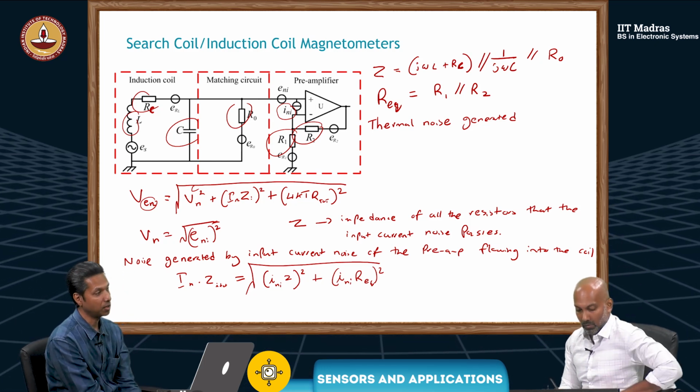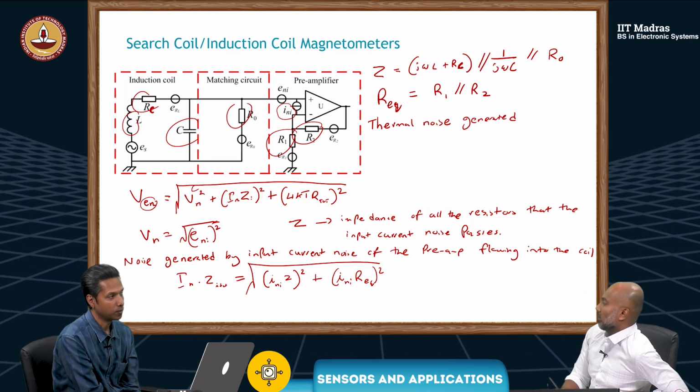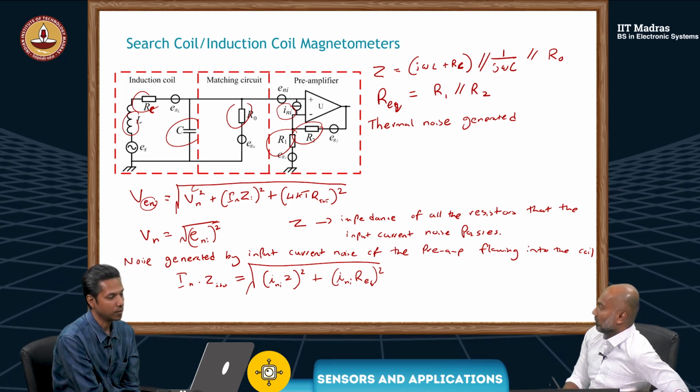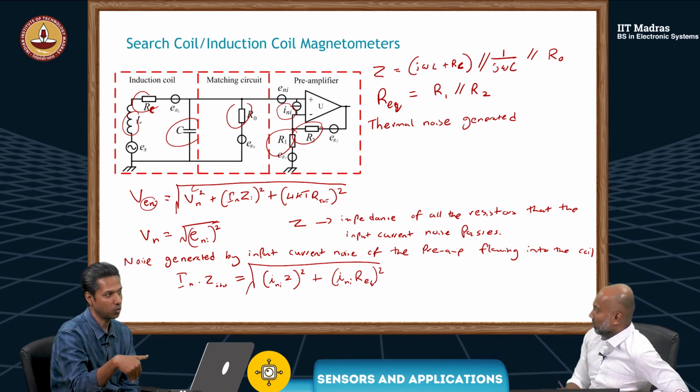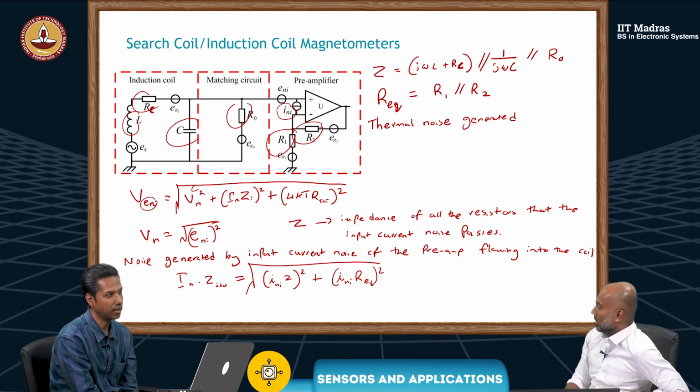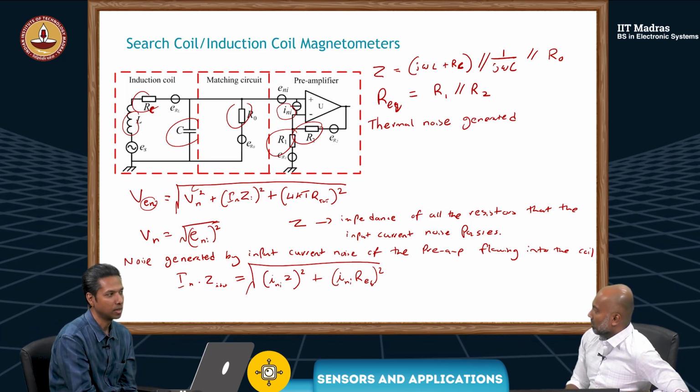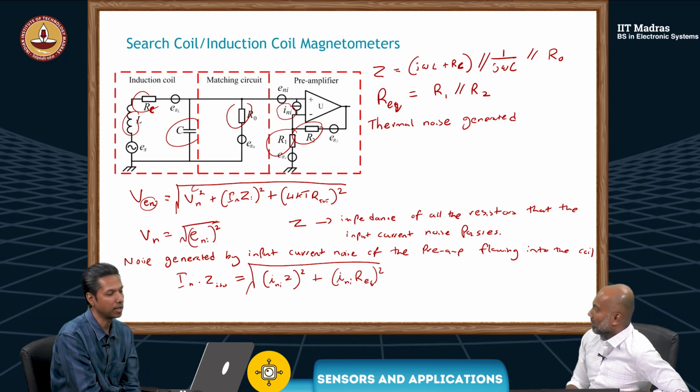Let's say for the gain, 1 plus R2 by R1, I may choose R2 10 times R1, some ratio, let's say if I want a gain of 11, or more than 100, some ratio depending on the gain I want.